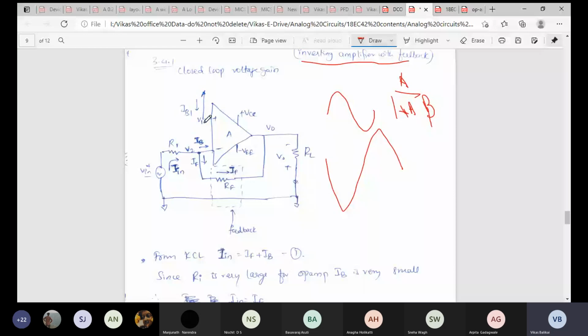If you can remember from your previous courses, basically in your basic electronics courses or in your third semester, the input bias current, input bias voltage, or output offset current and offset voltages are those certain parameters that will assist the op amp in the proper functioning of the entire circuit. Basically, if I want to ensure the op amp works as a perfect amplifier, I need to take care of the offset voltages and bias currents. These bias currents are those currents which result because of certain transistors that are present inside the op amp. So that is what bias currents are.